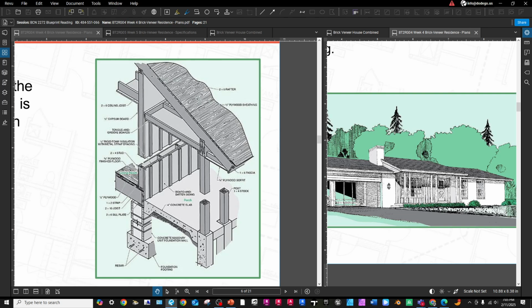So now the remaining dimensions for proper placement of the windows is going to be the height above the floor. So the typical wall section that you'll see on sheet 3 is going to provide the height above floor information for all the double hung windows in this dwelling.